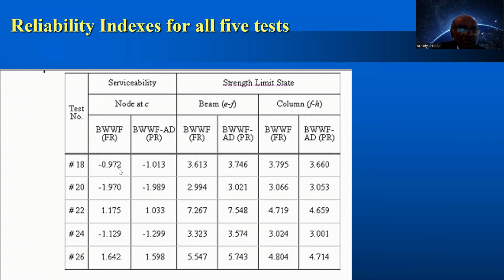You can see the reliability index in many cases for serviceability is negative, which means it is almost sure it is going to fail. Probability of failure is more than 50%. For strength, some of them are relatively good, but not as good as we want.